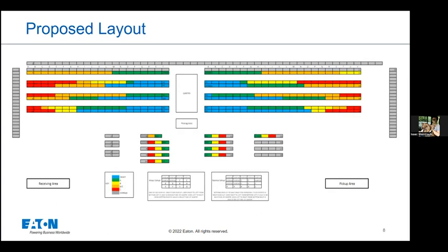We then made a spreadsheet with over 1,400 permanent locations for the different items. We used a U-flow layout in conjunction with an ABC analysis that we made. With the picking area at the center, we first had the heavy items close to the gantry, and then as you went farther away from that, it's the A movers, and then farther from that is the B movers, and then the C.